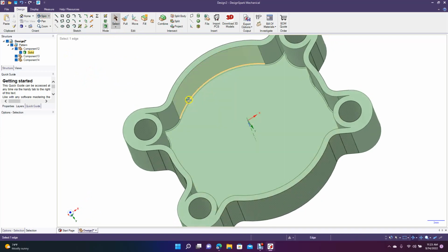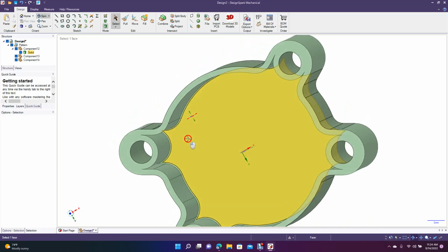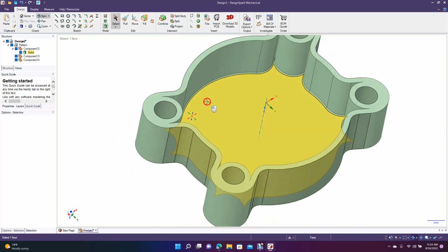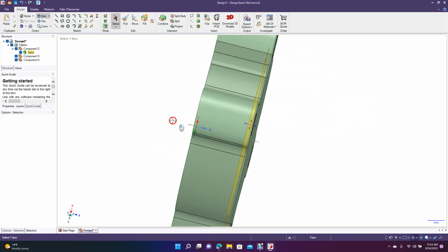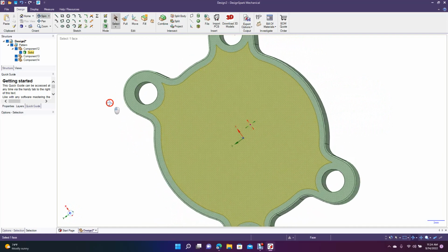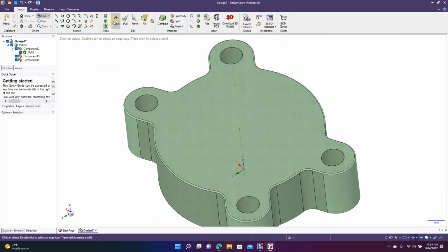And it's important to put fillets on places where sharp edges come together. That actually softens up the part, makes it more malleable. You're able to bend it without snapping. If this is a straight edge here and this is a straight edge here coming together, they create a sharp angle. So if you don't put fillets on that, it's possible that that could snap. Probably not on a model like this, but on any other kind of model, yeah, it's possible it could happen.